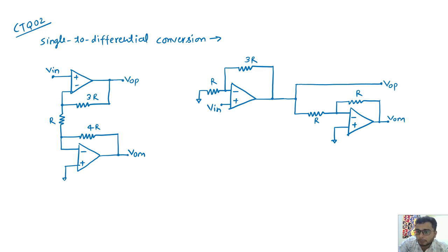so that we can compare two circuits, because input referred noise is ultimately very important, also the input referred offset, so that we can compare any two circuits. At the output, we can calculate the complete noise contribution or the offset, but we cannot compare two circuits depending on the output noise and offset, because there is a gain factor which is introduced in this output noise or offset consideration.